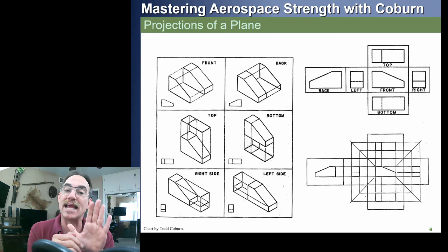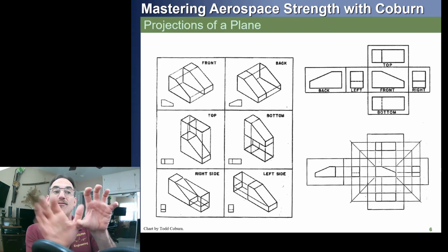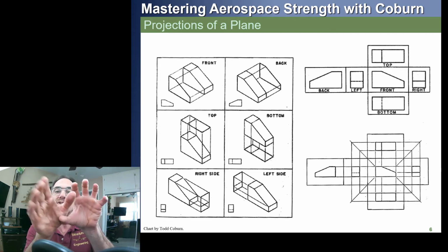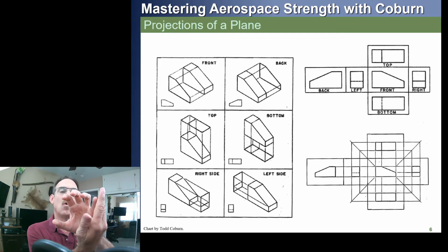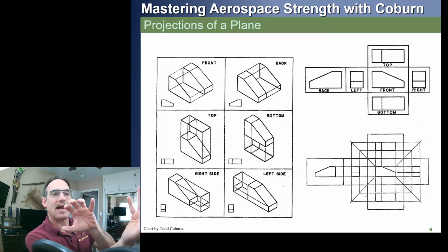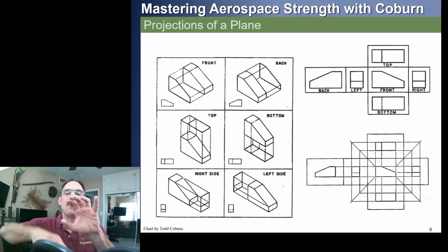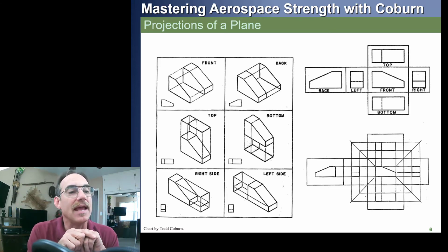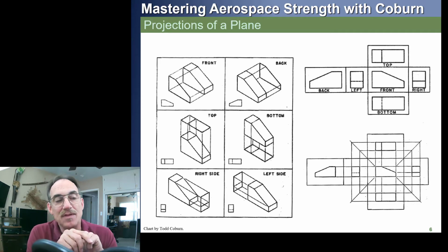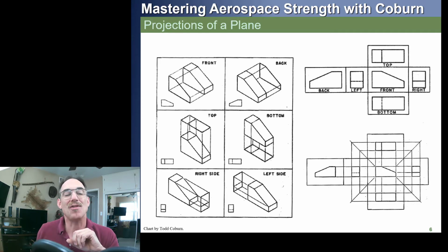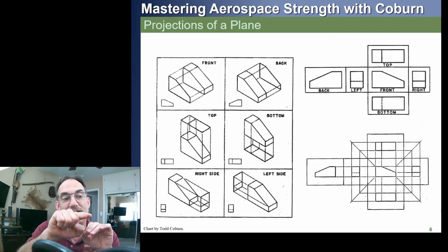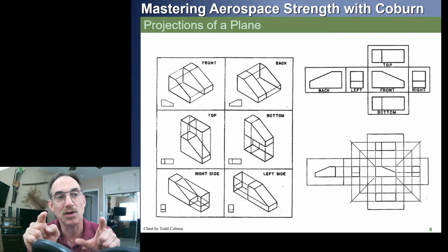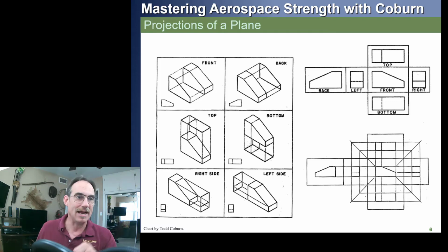Once again, we're going to take that front view, grab that first, and then fold it out. So look at this upper right, we'll see how we fold this part out twice, fold the top, and fold the bottom. That's how it works, okay? And when we're laying out these views, we can use what's called the miter line, which is this 45 degrees going between the true views. We're going to look at that again in more detail momentarily. You starting to get the picture? Stand by.